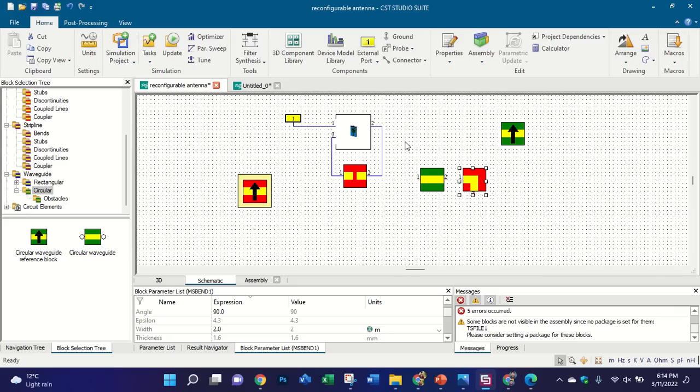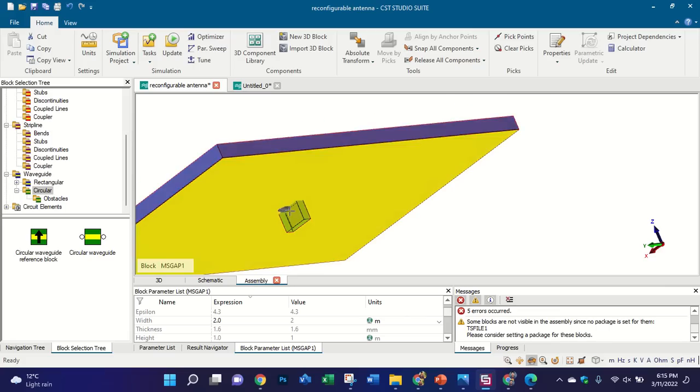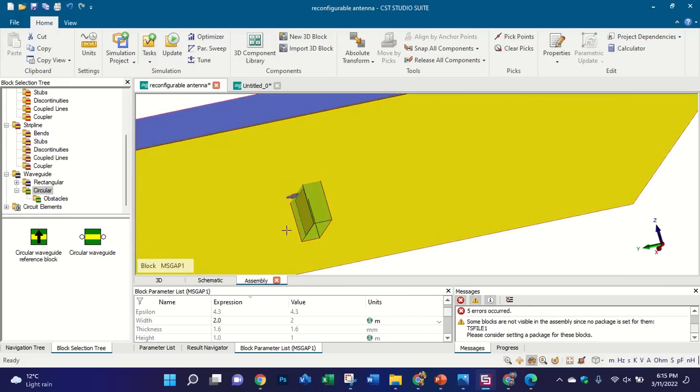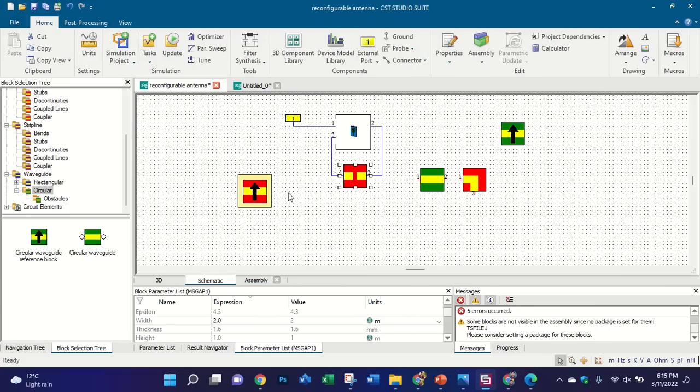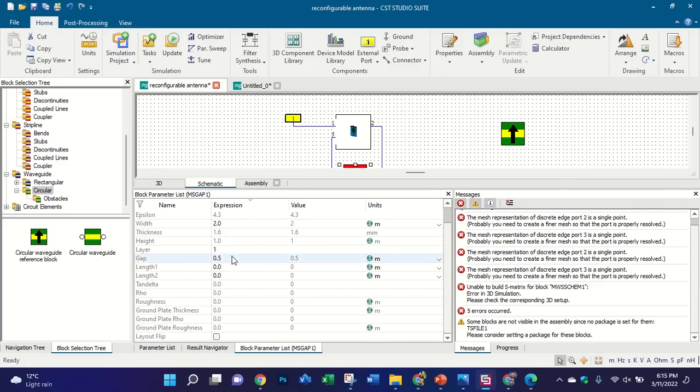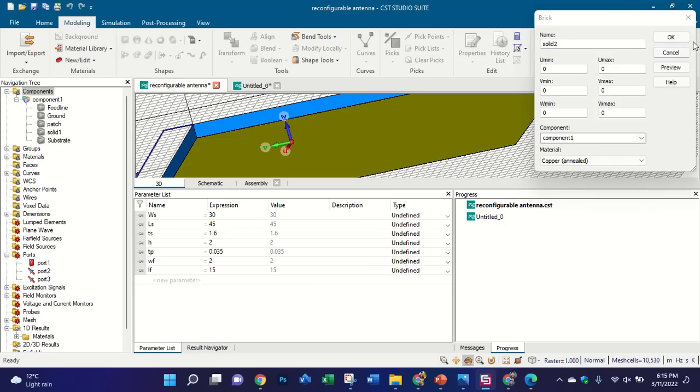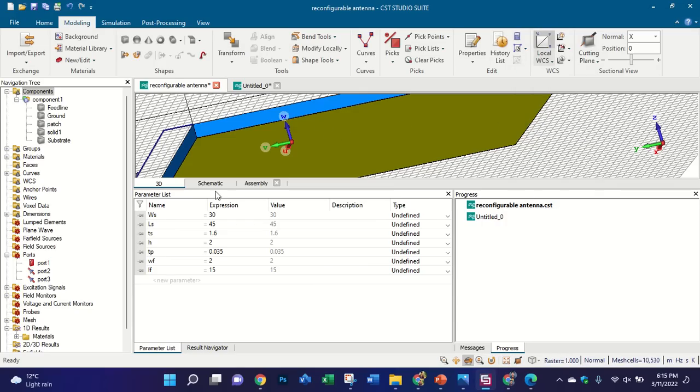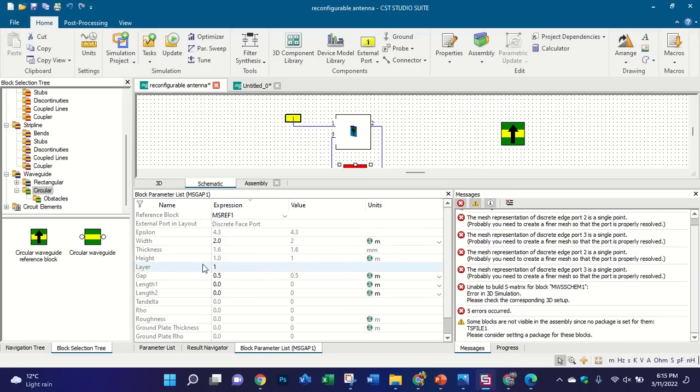Excuse me, Mr. Sarush, about the strip line. This is perpendicular to the antenna. Is there any configuration for the parallel? It must be parallel to the antenna. You are talking about this one? Yes. No, actually, I have wrongly written the dimension in this case. So you need to change your dimensions according to the substrate, so that it will be aligned with your substrate. Not parallel. I mistakenly chose other dimensions.